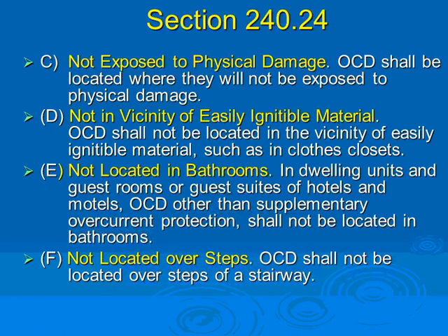Okay, a couple of other things that we need to do. Not exposed to physical damage. Your circuit breakers, you can't put them in a place where you can run a fork right through them. That's why you find on manufacturing floors when they have panels, they have these, what do you call them, guards, yeah, right around them because a fork can run into the MCC, which is sitting right there.